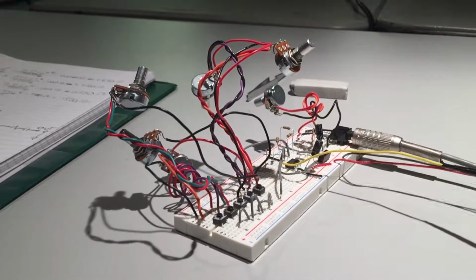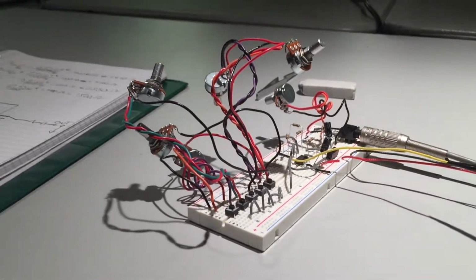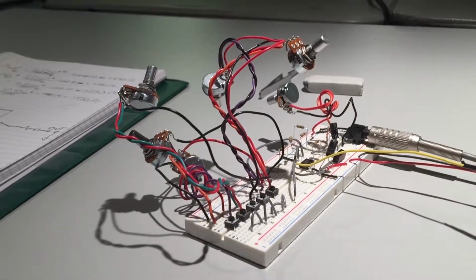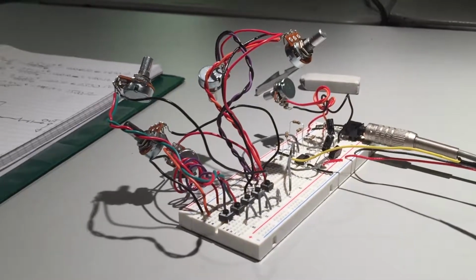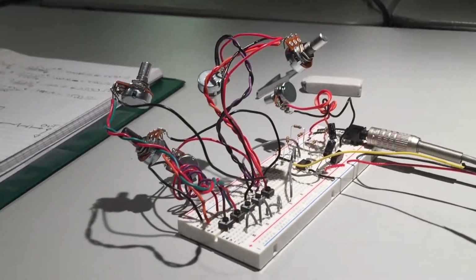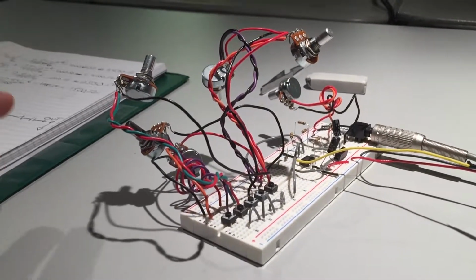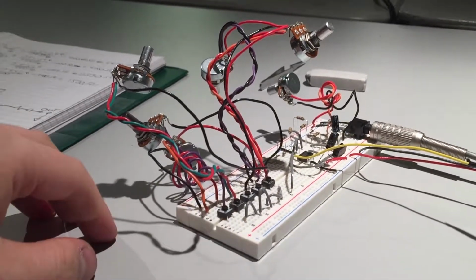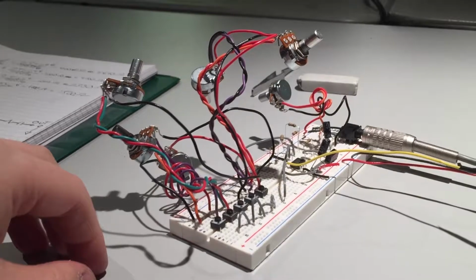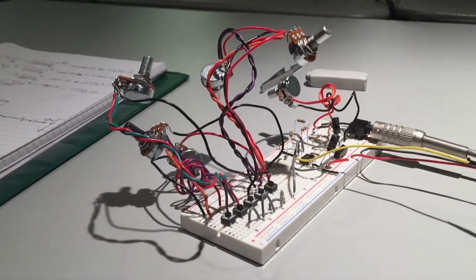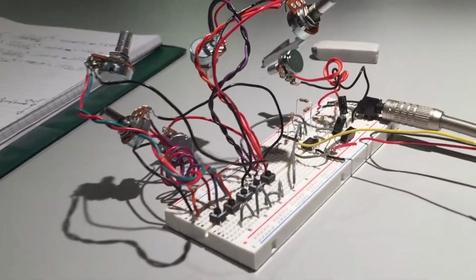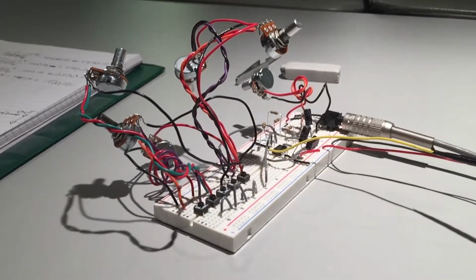As demonstrated here, the use of multiple buttons and different precisely controlled resistance values allows for the creation of synthesized tones via a simple operational amplifier circuit. Now let us take some time to adjust the potentiometers by ear and try to create as perfect relationships as we possibly can. These will most likely deviate from the values we determined originally via the multimeter, but that is okay because in the end what matters is how it sounds, not the numbers and the theories.